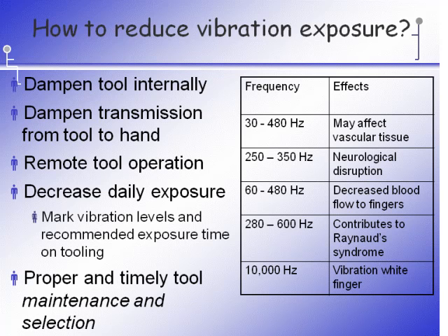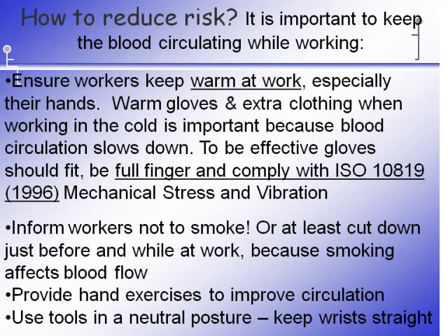And although we talked about hand tools, you can take this into a laboratory environment as well. Although they're not using power tools, when they're using maybe pipettes over and over again, can you have a pipette that has a button control instead of manually squeezing and opening the pipette? Can you pipette 4 things at one time instead of 2? Are workers in a neutral posture when they're using the pipette? So you can take this from hand tools and expand it into whatever area. Remember, whatever's in the hand, it's a natural extension of it. We want to keep the working point of the hands at about elbow height, slightly higher for precision work, slightly lower for heavy work, and to always maintain that tool.